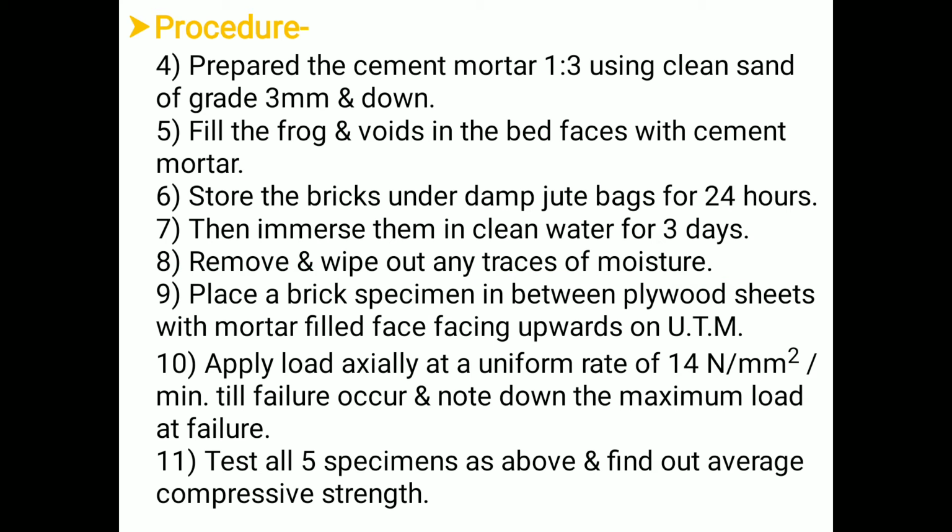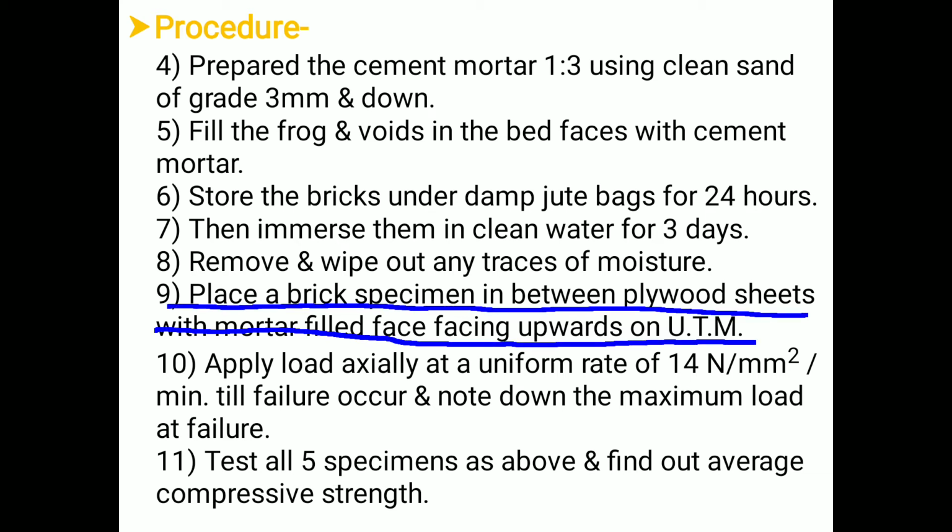Place the brick specimen in between plywood sheets with the mortar filled face facing upward on the UTM, or compression testing machine.